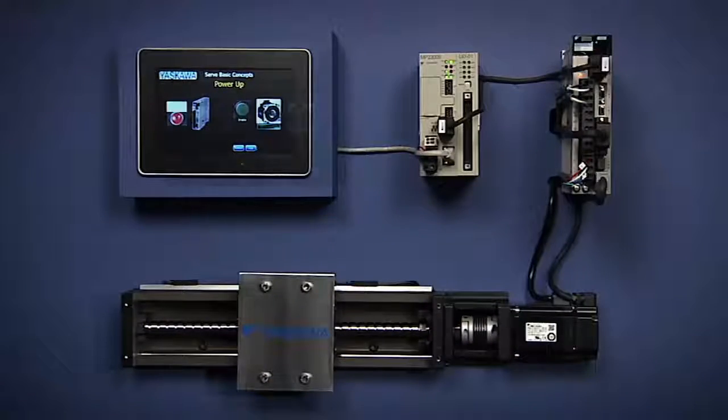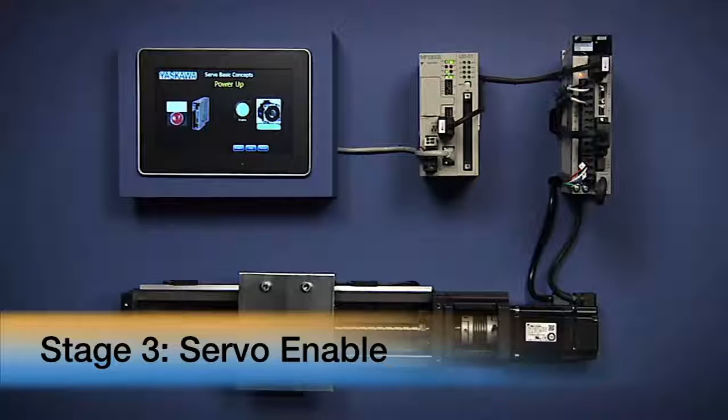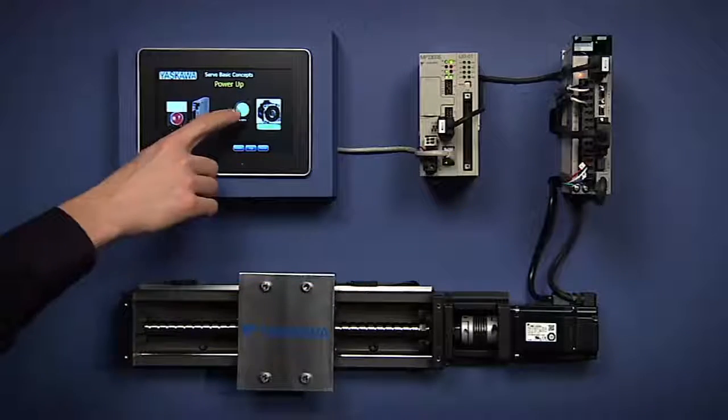The third stage is to energize the servo motor. We refer to this as servo enable. This signal to enable the motor comes from the controller. Servo enable doesn't mean the motor is moving. It only means that it's ready to move when commanded.